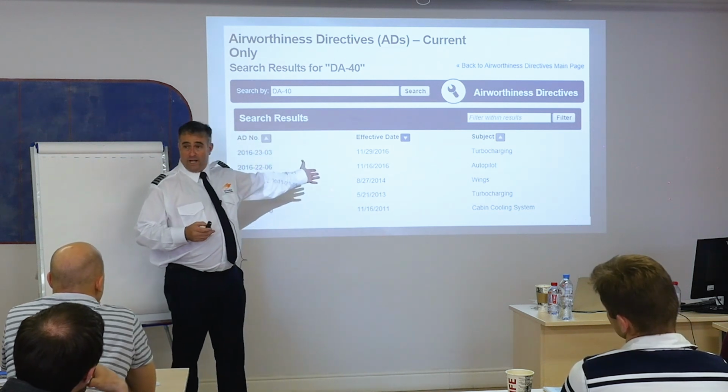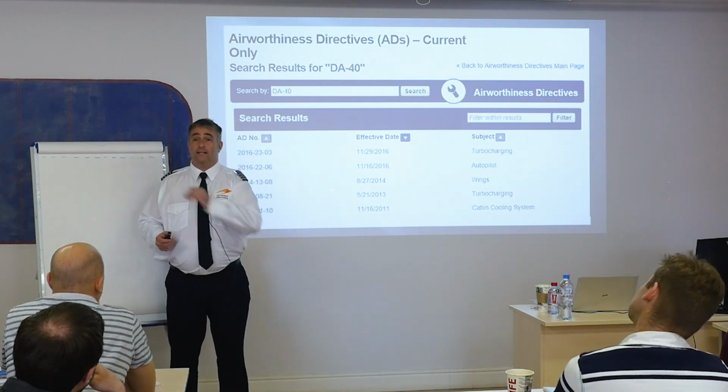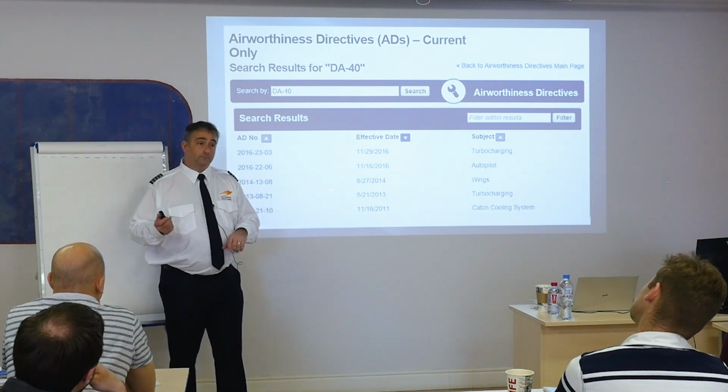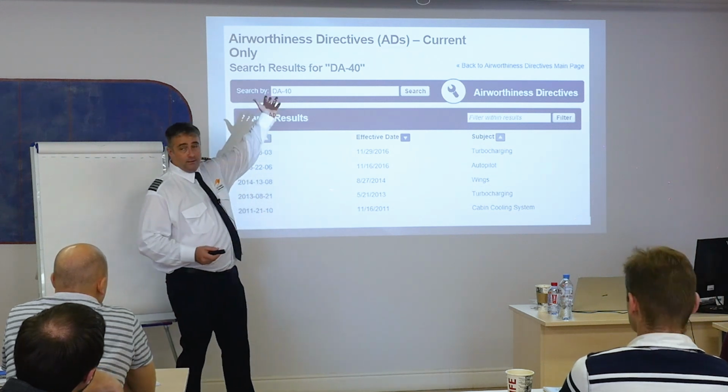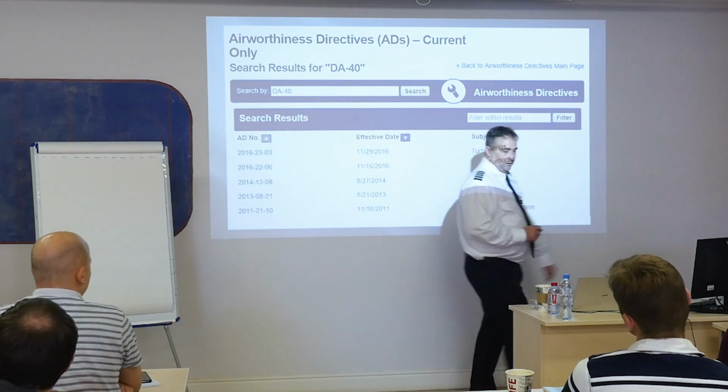Well, then the FAA says, okay, we have to have an airworthiness directive. Everybody that owns that kind of Cessna 172 has to change the seat tracks. Okay? So I could find it on the airworthiness directive registry page on FAA.gov. Okay.